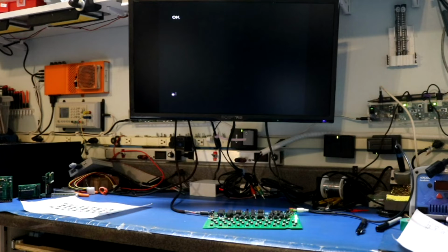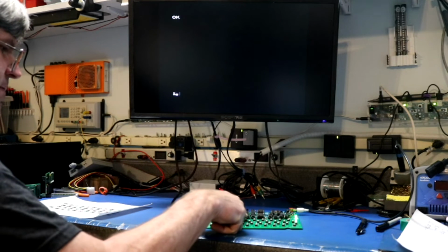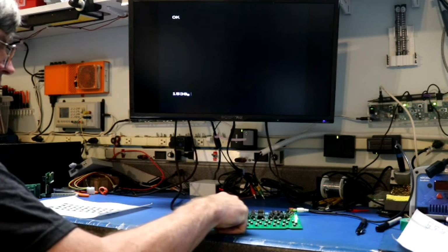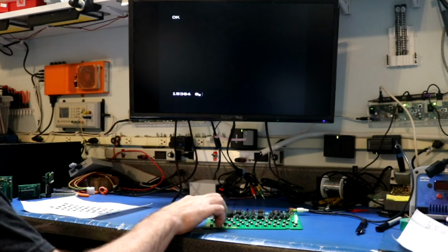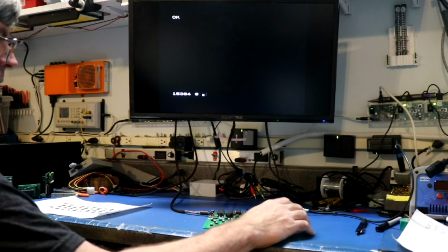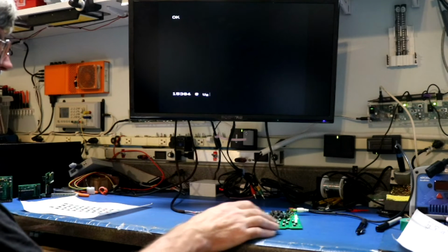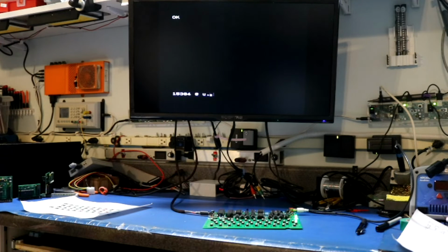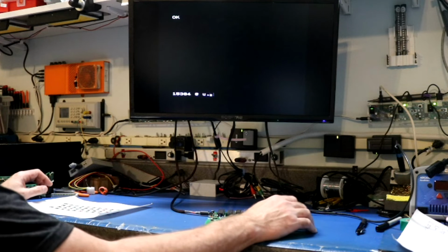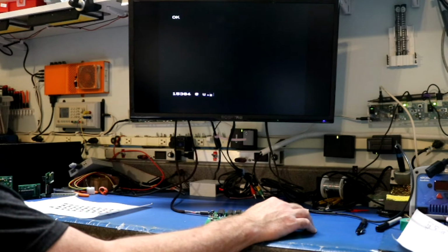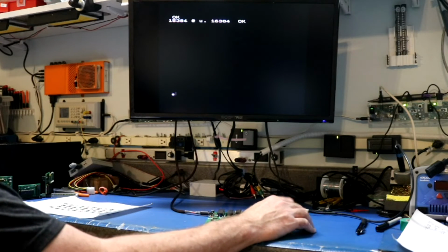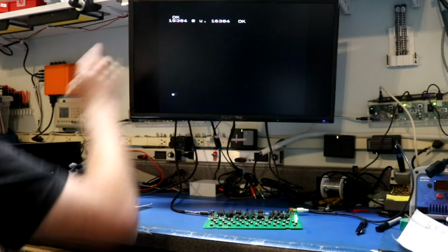Okay, let's try out the RAM expansion first. This is actually very easy to test. If we do a 16384, and then let's do an at, u dot. This will print out what it thinks is the top of RAM, which should be 16K, 16384, on an unexpanded Jupiter Ace. So there we go. 16384 is in that location.